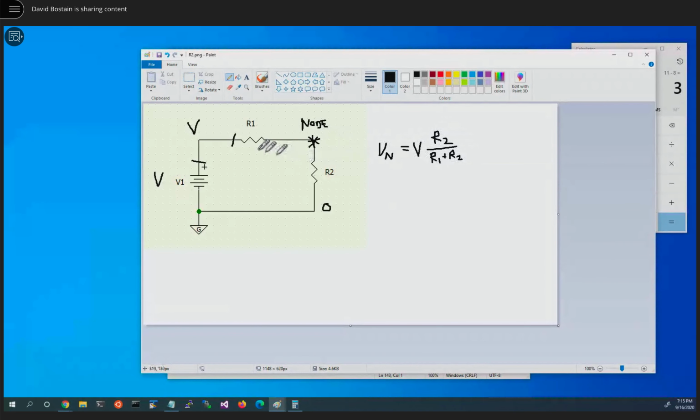But the idea here is that if we sum these two resistors together, basically we're replacing them with the equivalent of a single resistor, right? That would have been replaced with a single resistor that has a total value. That's this. And if R2 is taking some proportion of that, we put it over the top, that'll fractionally tell us of the total how much is attributed to R2. That proportion can then be multiplied times the voltage dropping across both of them to tell us how much voltage was dropped right here. So this formula comes in handy if we have a proportion.